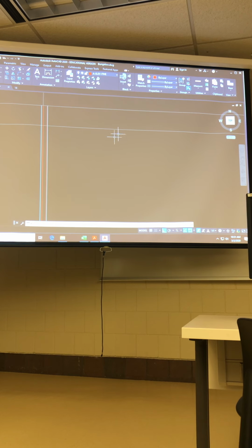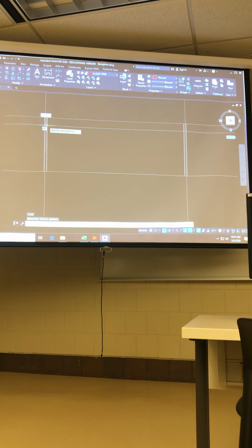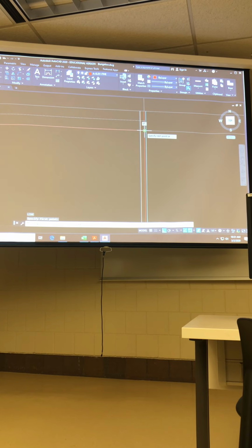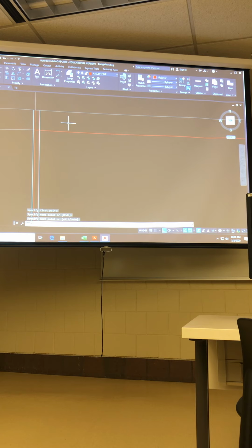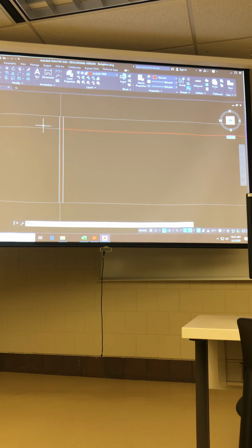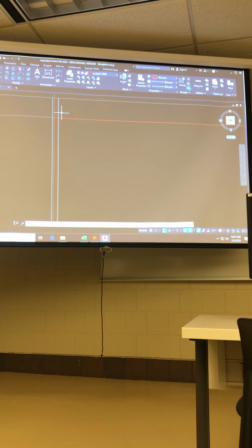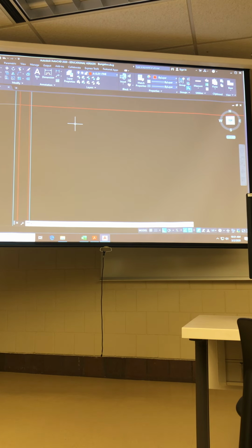So I am going to, at this point, go ahead and draw a line, and that is the underside of my truss for the upper floor level. I can now offset that line for the thickness of my gypsum board on the ceiling of the main floor level. And what is that thickness again for ceilings? 5/8. Thank you.